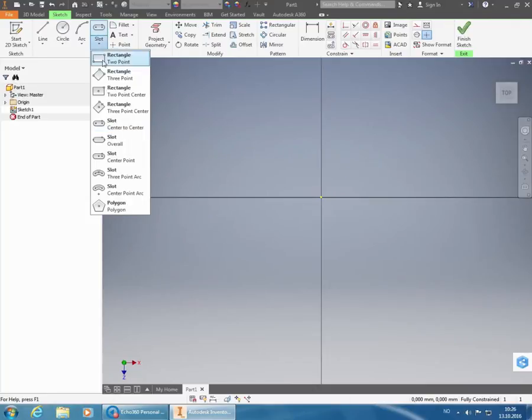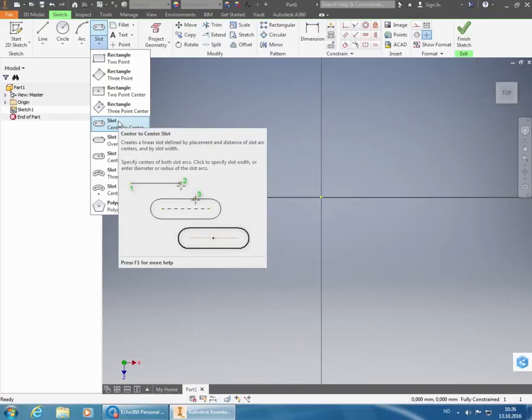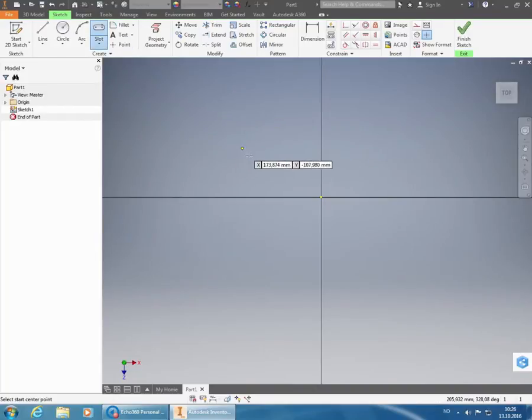Doing the width first. I'll have to check this one. Let's see what it says. No, we're going to do from start to finish there. Let's see here. So we start, and then we have the 65 millimeters. We lock it into place. Press enter, and then we get to set the diameter of it. And the diameter is going to be 35. Lock it into place with the tab button, and then I get it in there.